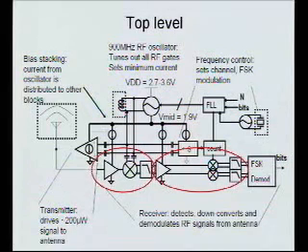So typically what you have to do in any system like this is assume your receiver is on a little longer than you absolutely need, to cover mismatch in timing. You might turn on 5 milliseconds early. If the other guy is in fact 5 milliseconds early, you're okay. If he's 5 milliseconds late, then you're just on for 10 milliseconds doing nothing, and then he wakes up. But usually it's actually more like microseconds. So that's how you do it.